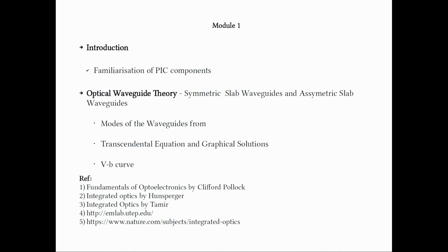So in this case of asymmetric slab waveguide also we have taken a parallel approach as that of a slab waveguide, but of course we know that is more general, and in particular there is a cutoff V number, so to say, below such V number the light is not guided in the asymmetric slab waveguide. And we once again have seen several properties as a function of the asymmetry parameter and so on and so forth.